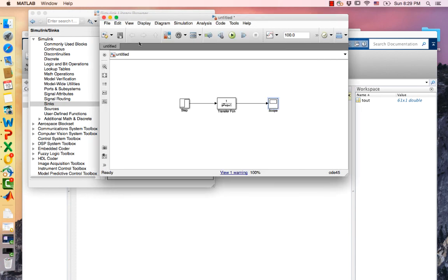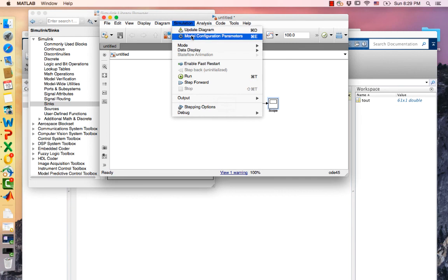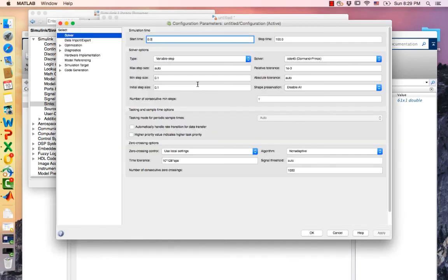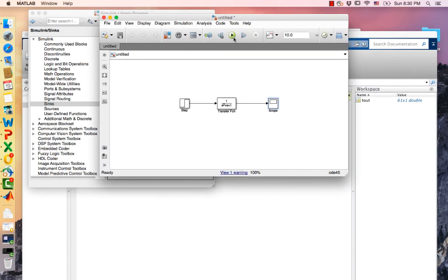And the reason behind it is we changed our simulation model configuration. So I want to use a smaller step size, let's say 0.01, and again I set 0.01. The time, instead of 100 seconds, let's say I change it to 10 seconds, just like the default number. Sometimes you need to play with these numbers to get a good curve. So let's try it again.